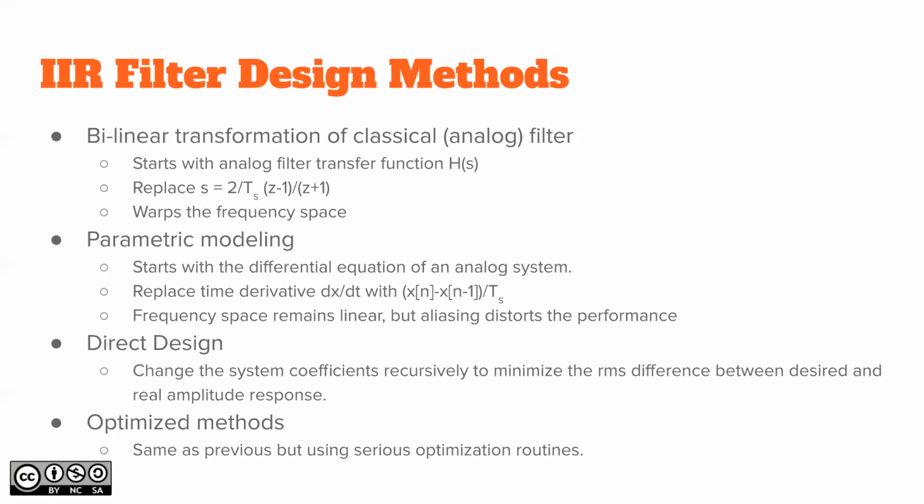So when you use the Laplace transform on a differential equation, you actually get the transfer function. But anyways, it starts from the differential equation and then replaces the time derivative with a discrete time derivative, a first order derivative here. Okay, so the first order derivative would be this one, and the second order would be this squared divided by Ts squared, and so on.